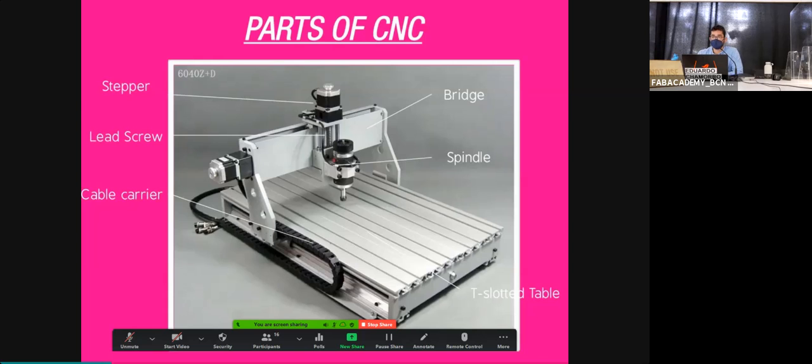The machine is really strong, and actually, if you jam the cables or they get attached to something, the machine could easily break the cables on its own. And usually the spindles are 400 volts or 240 volts, so you don't want to break these cables. You need to be always careful not to get the cable carrier attached to anything or trapped in something. For example, once I got trapped by the cable carrier, I was not paying attention. Basically, I broke my t-shirt. Luckily, it was only the t-shirt. I stopped the machine fast enough, but you need to be always careful about this.